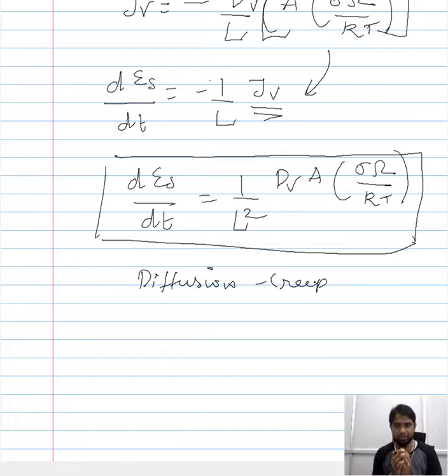So the fundamental factor that governs the diffusion creep mechanism is the difference in the concentration of vacancies. This difference is introduced because of the role of stress. When there is a tensile load operating, because of the Poisson's effect you have a compressive load, and this difference in the signs of the mechanical condition brings about a difference in the concentration of vacancies. Because of this, there exists a gradient. We have simply considered a line over which a gradient exists because of this difference in the mechanical condition.